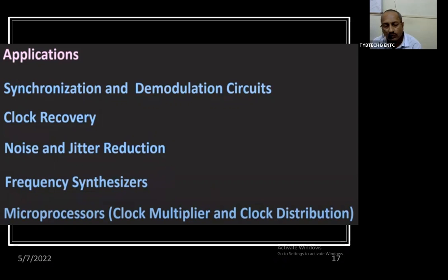This is where the clock multiplier comes in. Even though the processor is there, to process instructions there should be a clock signal, because each instruction requires some specific number of clock cycles to execute. If there are more clock cycles per second, more instructions get executed per second.